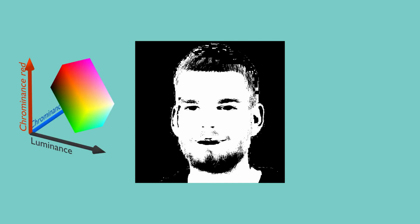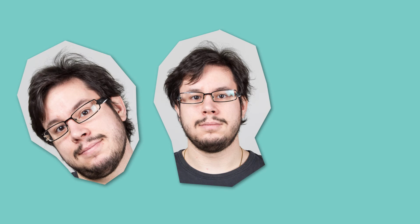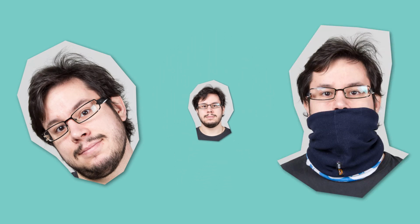We ended up using skin color segmentation since we were to take bust photographs of our subjects, so our goal was to isolate skin regions from non-skin regions. Our research suggests that the most powerful feature in face detection is skin color. The ideal color space is the YCbCr color space, as it corresponds most to human visual perception. Y stands for brightness, Cr is the red component, and Cb is the blue component. The power of skin color segmentation lies in its property of being effective after rotation, scaling, and partial occlusion.